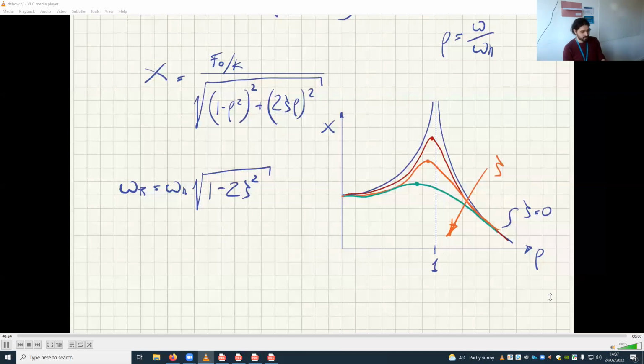See, because if you have a lot of damping, it will never break, because this amplitude might not be enough to break it. In fact, if you're holding it, it will never break. Just the simple fact of holding one object increases its damping level by a lot, because your hand gives a lot of damping to the structure.